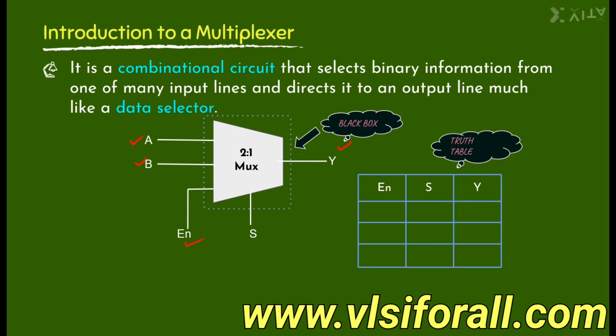So for 2:1 MUX, that is the simplest of all the MUXes, we have 0 as the enable. That means when enable is 0, there is no function being held in the entity, and hence whatever the value of S may be, Y shall always be 0, right? Next, when enable is 1, if S is 0, then Y has to be A. This means that S can be 0 or 1, because this is just one entity that will select a value from A or B. So that when S is 0, A becomes the value which is to be given to Y. And when S is 1, B becomes the value which has to be given to Y.